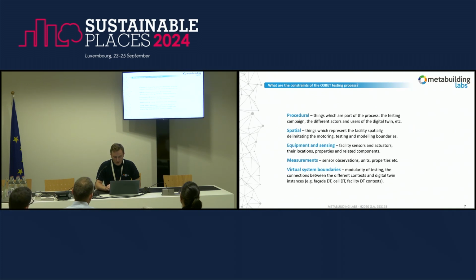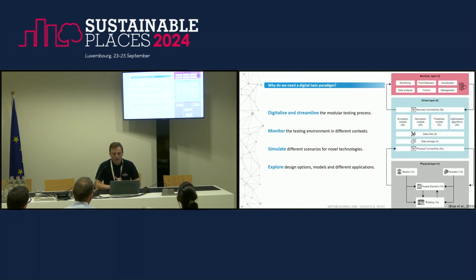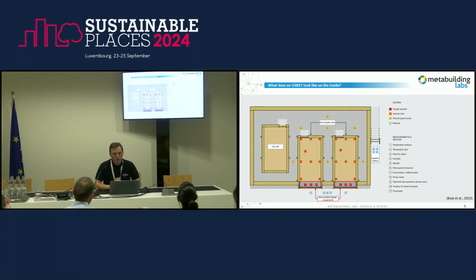In our case, I'm going to go back to, you see there that I have sensor and actuator. So we tried to be a real digital twin on the physical side. The problem is that we rarely want to actuate anything in this context. However, the things that will be actuated, if necessary, and that probably will happen as a rule-based actuation, will be related to the conditioning of the zones. So the thermal zone, that is the guard zone around in gray there, and also within the cells, there are radiators and ventilators that need to have a set point temperature, for example, and humidity.